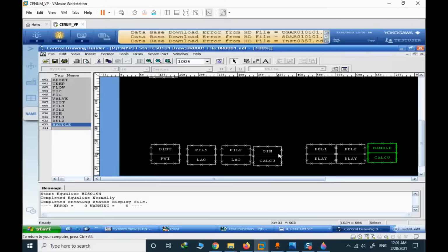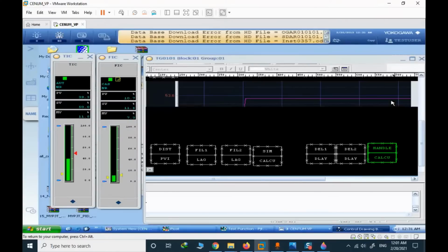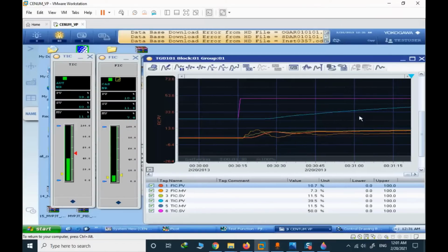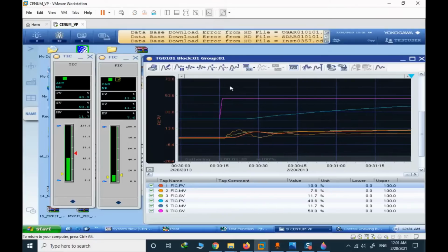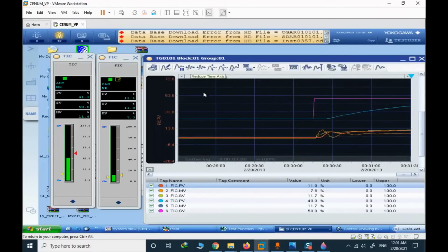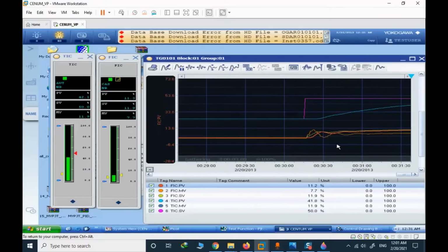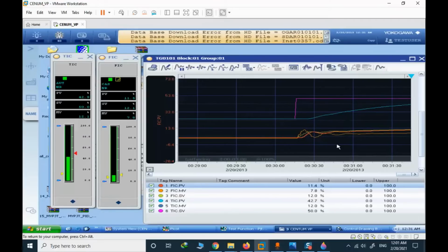You can change the time constant for the flow, time constant for temperature. You can change the gains, and also the PID parameters can be changed in the function block. I used two calculation blocks in order to handle some special cases in the Cascade.